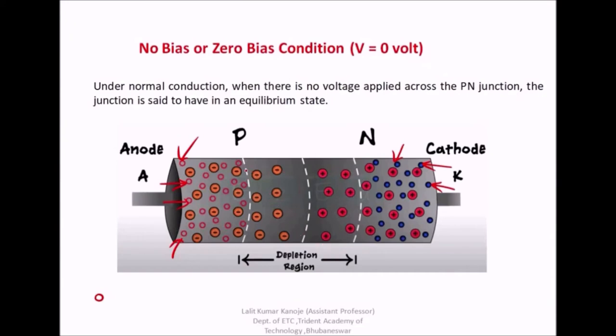You can see this white boundary; inside it is called the junction. Inside the junction we have only negative charge in the p region and only positive charge in the n region. So this is what happens when a p-type semiconductor is connected to an n-type semiconductor.